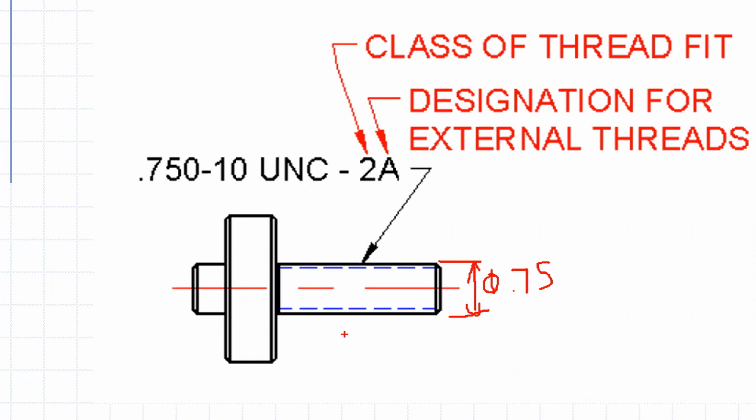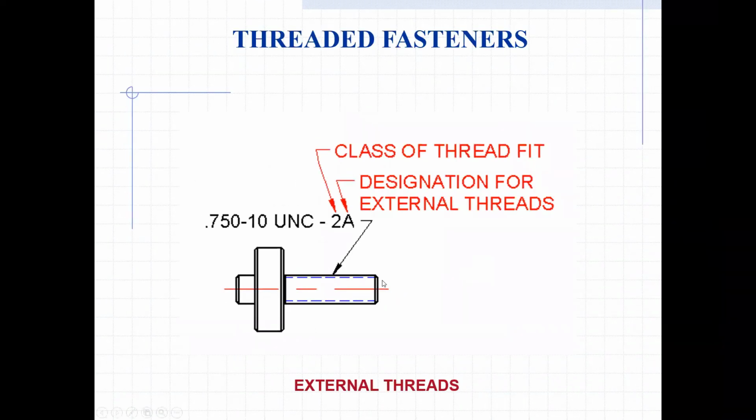But that nominal diameter is the size of the cylinder. Same way with a hole. That nominal diameter is the size of the hole. And the real logic for the hole is the outside, the hidden line diameter should be the nominal size, and then the object line should be a little bit inside. Again, I need to be able to distinguish those two, but I don't really care. You can look it up and make it exactly right, but it really doesn't matter, is what I'm trying to say.